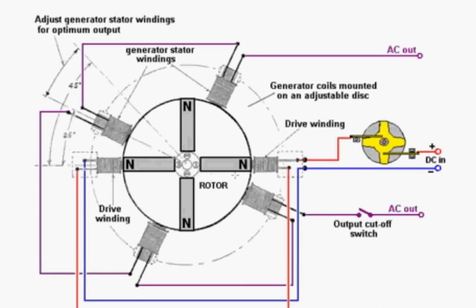Now that's fine as it goes, but then the rotor continues on round. And the cunning part on this is the power to the drive coil is then cut off. And when it's cut off, you get a back EMF pulse in the coil, and that reverses the magnetism of the coil, and that pushes the rotor on its way instead of hindering it.